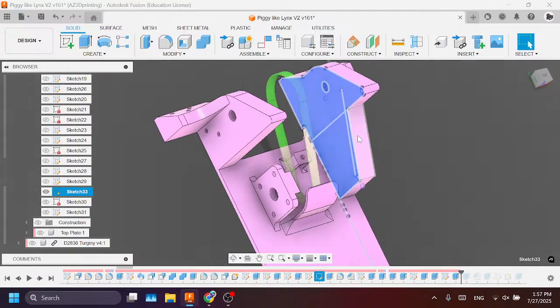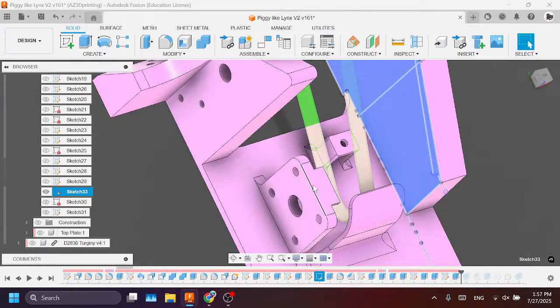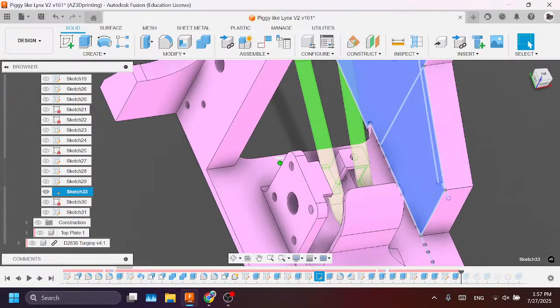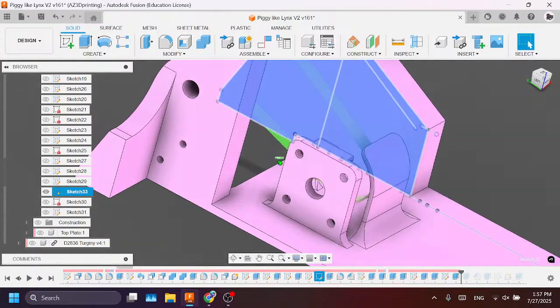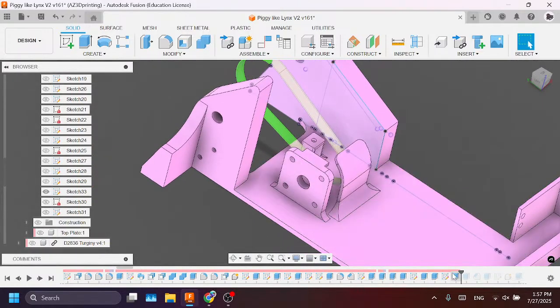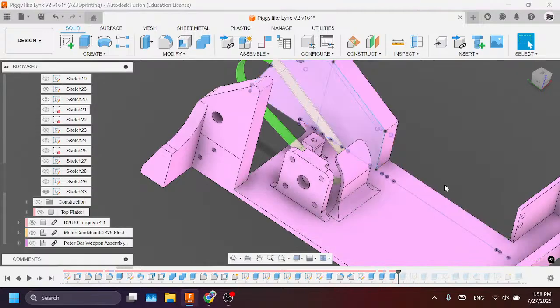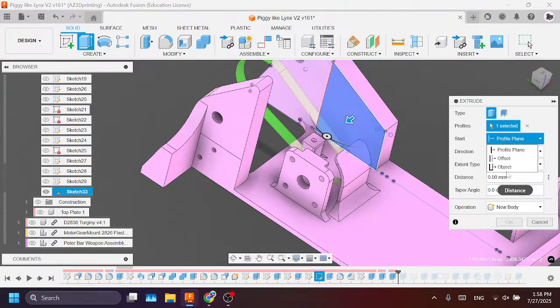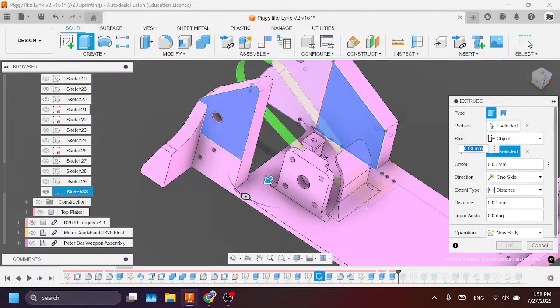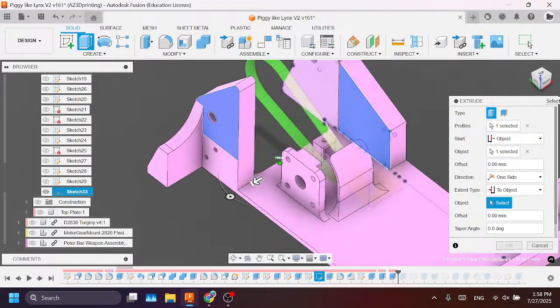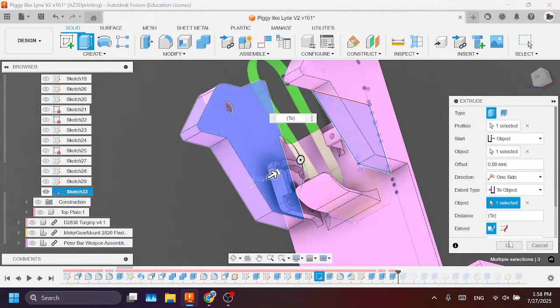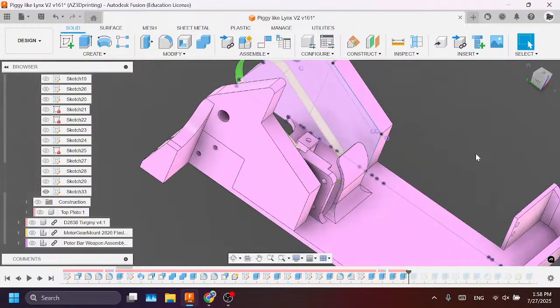Okay, so we're trying to look at this guy, and we don't want to block off this motor mount here. So actually, I think what I'm gonna do is that extrusion, which happened, I'm not sure where. Here. I'll repeat this thing, and then what I'm gonna do is cut a little cutout here, and then I'll cut a cutout so that the motor mount can be fastened properly.